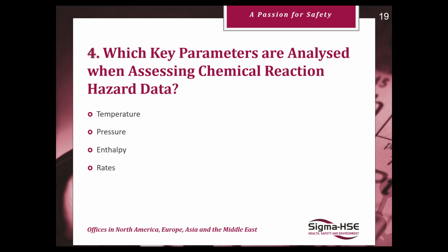Adiabatic temperature rises that we discussed a little bit before. Every reaction is allowed to proceed adiabatically and heat up its own mass. What is the adiabatic temperature rise going to be? We can also do some assessments isothermally.